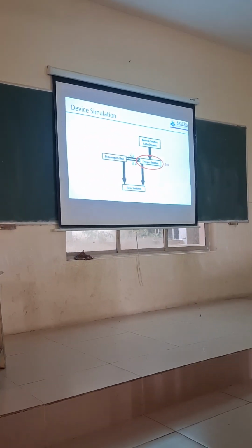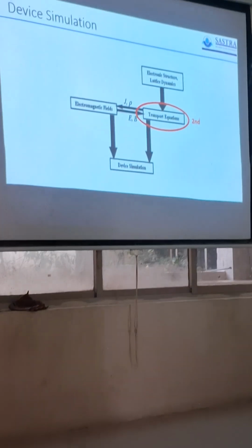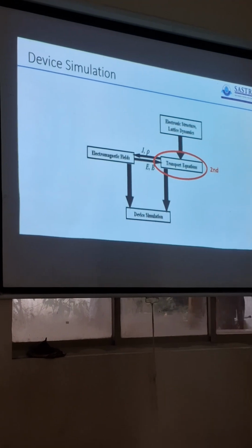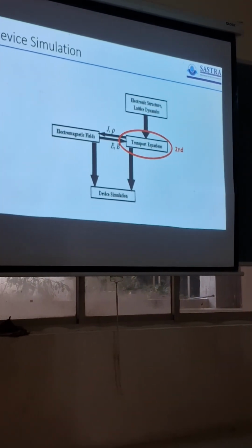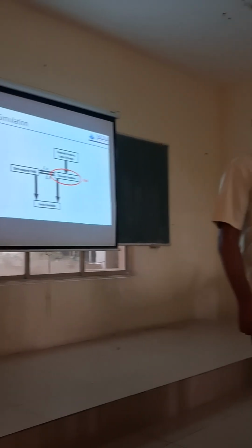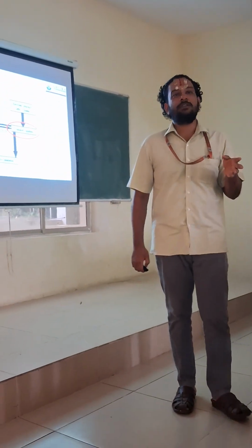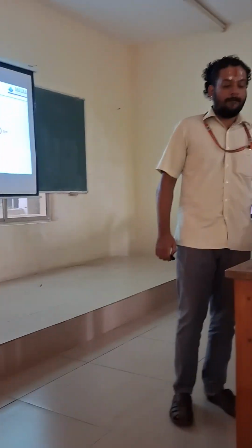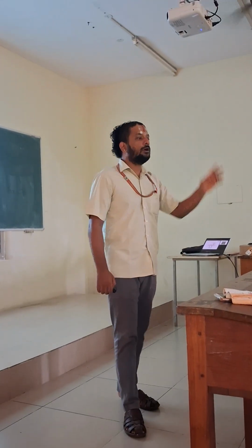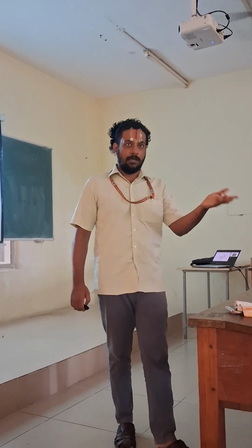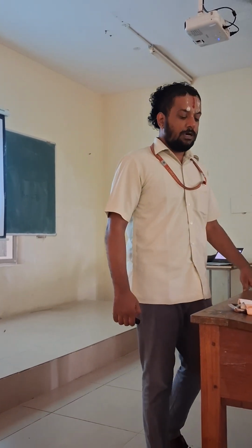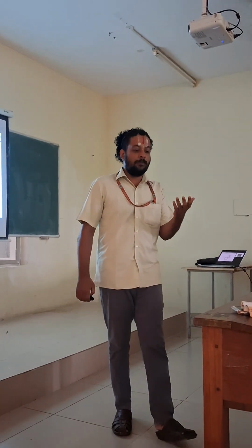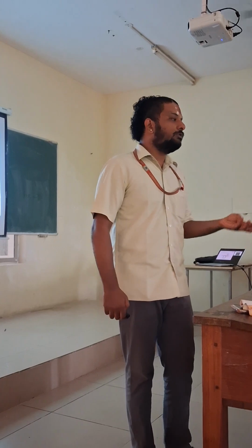So the electron structure lattice dynamics. Basically, we need to calculate the band structure of the device, the equilibrium band structure of the device. We use various different abstractions, levels of abstraction, depending on the simulation complexity of our transport equations. For example, if I'm using a quantum solver, I probably have to use density functional theory based band structure calculations. If I'm using a Monte Carlo based approach for the Boltzmann transport equation, I probably use a tight binding or an